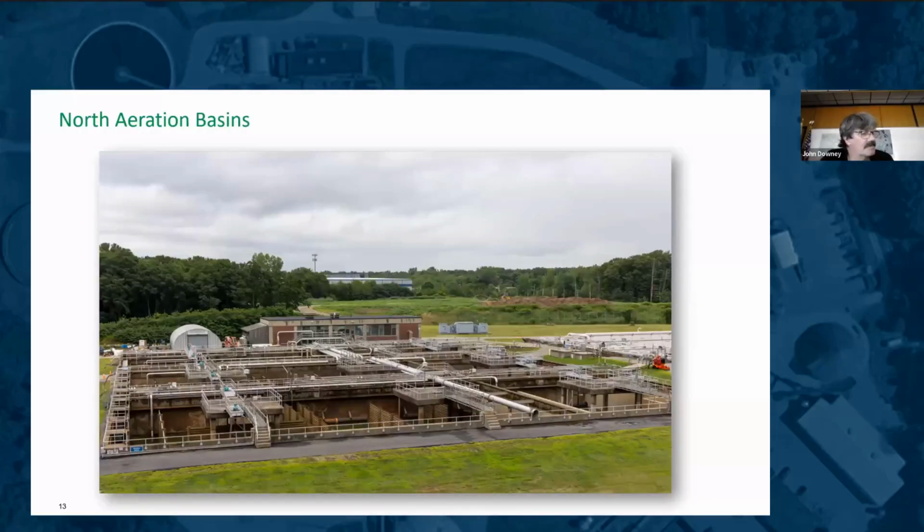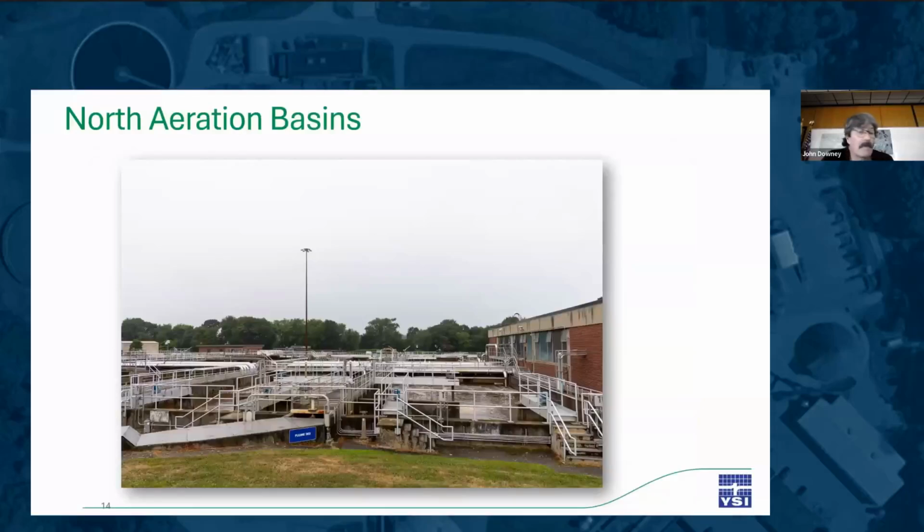While these 4 basins are fed from a common source, they are 4 separate environments. This is owing to the way they're fed. You can see those covered flumes are at an angle to the basin head, and the flow is further directed by a rudder at the end of the chute. Perhaps it's more of a suggestion than a direction we give it, because the water seems to go where it wants sometimes, but we get pretty good filling overall.